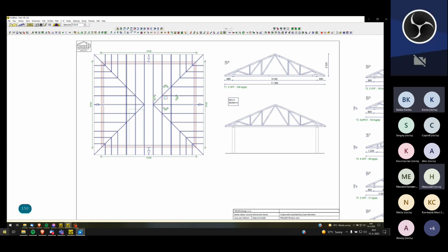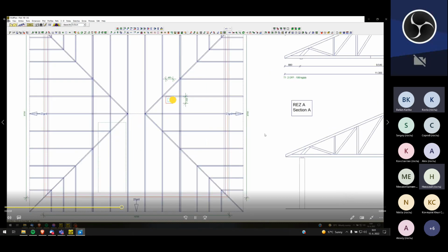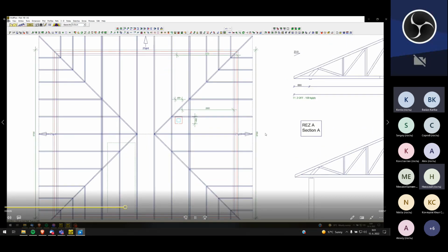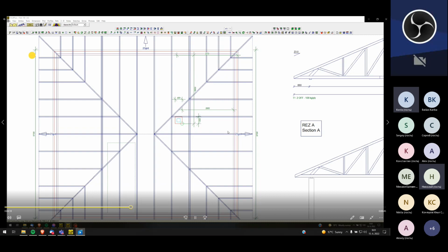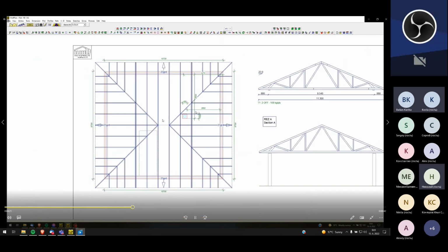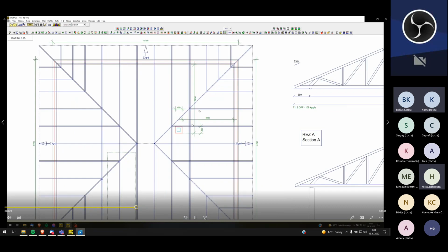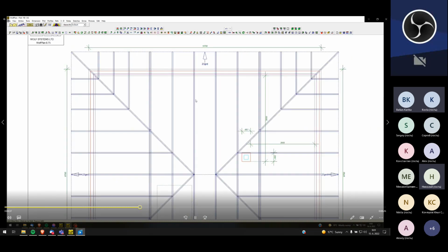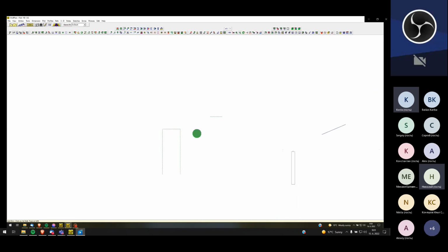This Wolf plan will go for static as well, but for static we need more information. There's a sketch of the truss. There's a section A. This information accompanies the static calculation or goes to the checking engineer, so more detail is needed. You can see there is no infill on the roof. Maybe there's a problem here at the chimney, but they can cut it on the side and use that piece of timber to move it 5, 6, 7 centimeters away from the chimney.